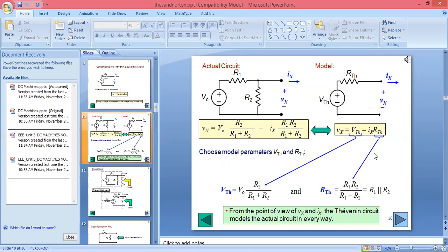So here, when we are having the actual circuit, the same circuit I am writing, we can convert that into this form, where we will get the equation Vth minus Ix Rth. That is nothing but the voltage drop that will be across Rth. And what we are saying, when we are giving the voltage, at that time some potential will drop across the Thevenin equivalent resistances. Across whatever resistances are there, there will be a voltage drop when we give the voltage. So you will get the equations for Vth, Rth here.